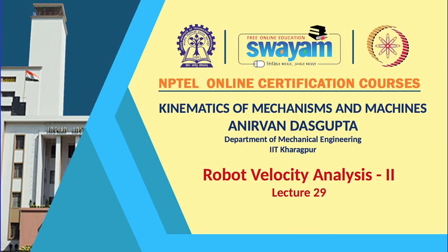We have been looking at the velocity relations of robot manipulators, and we have observed that we can relate the joint velocities to the end effector velocities through the Jacobian matrix. Now, this Jacobian matrix we have found is dependent on the configuration of the manipulator.